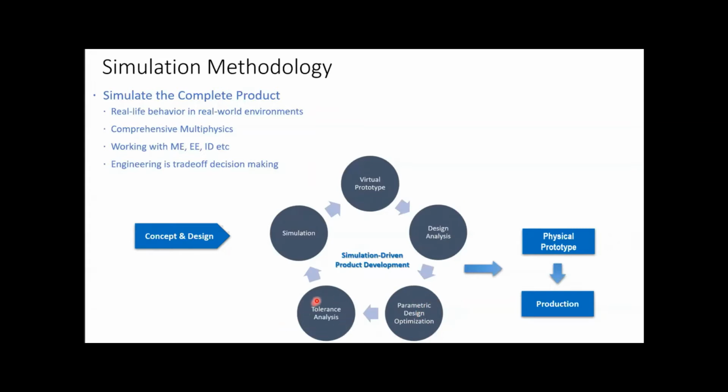We'll also look at tolerance analysis, because we are building a real device. We must simulate what happens when we build, say, 1 million of these. How does the antenna vary depending on the batch of the build? You know, each component has a tolerance. It has a mechanical tolerance, has electrical tolerances. All that goes into the simulation, and we go back to the start, and we run this development probably for 4 to 5 to 6 months before we even kick the program off.